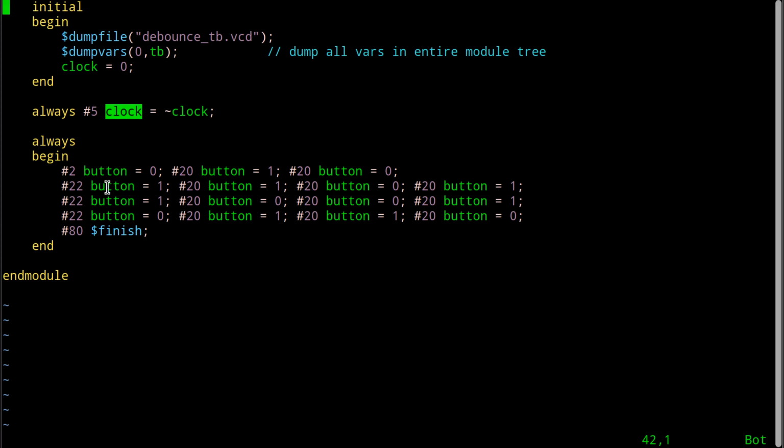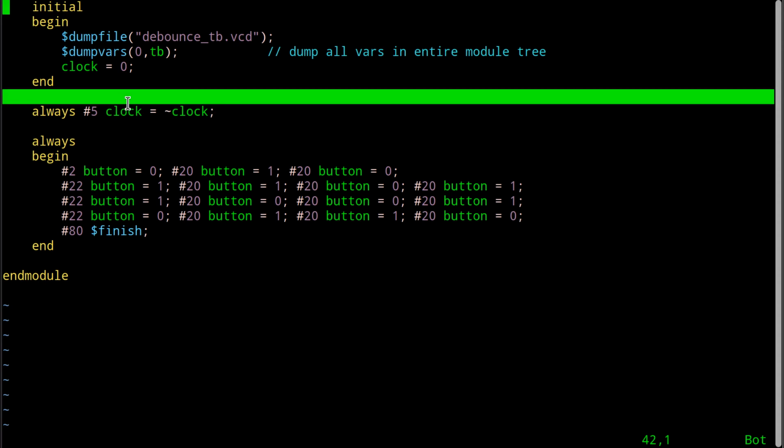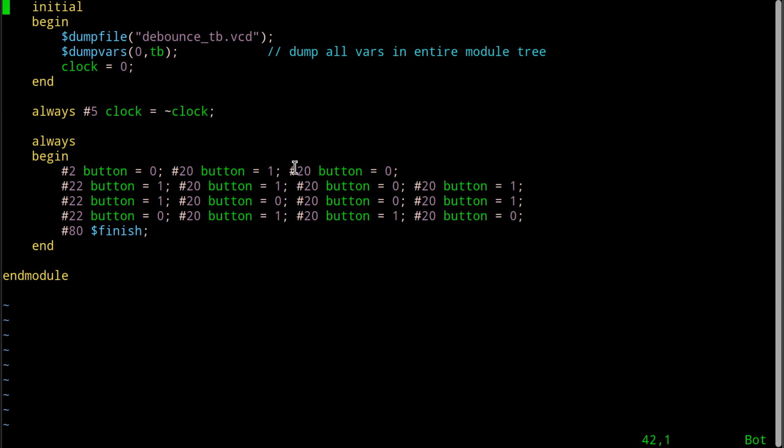Okay, this is not the best test bench. You probably should put some cases in here where it does co-align with this to make sure that doesn't do anything weird, and move it around a little bit, jitter it around a little bit to make it more realistic. But the bottom line is it'll either move exactly at the same time there's a sensitive edge on your system clock, or it won't.